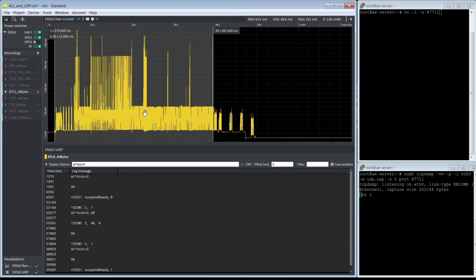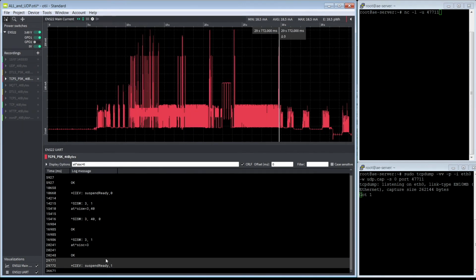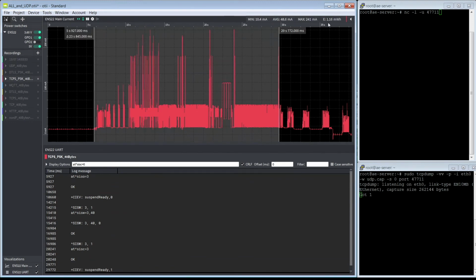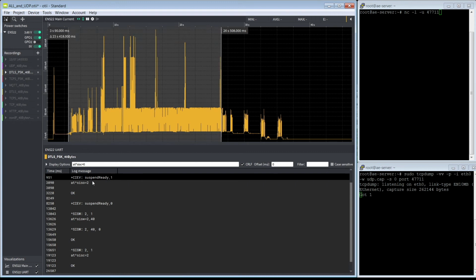I can make it a little bit simpler if I use a pre-shared key, the so-called PSK. With TCP and PSK, I go down a little bit to 1.1 milliwatt per hour, and the same is possible with DTLS, so secure UDP. This is around the same amount of power which I need to set up this DTLS connection. The difference is that with a pre-shared key, the key which is used to encrypt is known on both sides already, and therefore we do not need so much energy and much fewer packets to be sent to get the crypto part up and running.